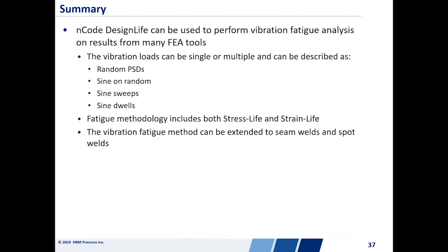And with that, I just want to cover a quick summary, and that is to say that what we've seen in the demonstrations and the slides here is that nCode DesignLife can be used to perform vibration fatigue analysis on results from a wide variety of FE tools. The vibration loads can be single or multiple, and they can be described a number of different ways. Those ways are random PSDs, which is probably one of the more common ones, potentially sine on random, sine sweep, or sine dwell. The fatigue methodologies can use both the stress life and the strain life material definitions, and vibration fatigue methods can be extended to things like seam welds and spot welds.